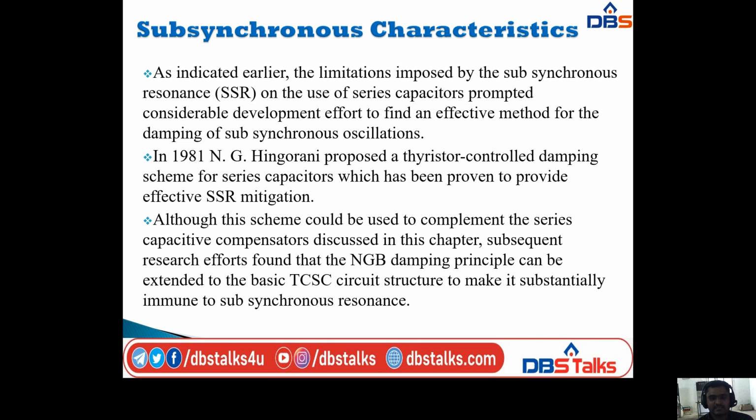Although this scheme could be used to complement the series capacitor compensators discussed in this chapter, subsequent research found that the NGH damping principle can be extended to the basic TCSC circuit structure to make it substantially immune to subsynchronous resonance.